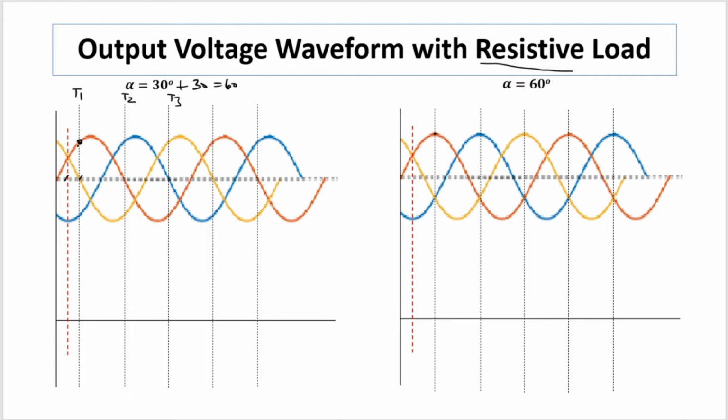So we'll consider the ideal conditions, and when we trigger thyristor T1, T1 will be conducting till 120 degrees. But what happens from this point of triggering till 0, till when the level of voltage becomes 0? It is the case of a pure resistor, so when voltage becomes 0, current will also fall to 0, and under these circumstances the thyristor will be turned off. But from this point thyristor T2 will take over, so ultimately the voltage level will shoot up.